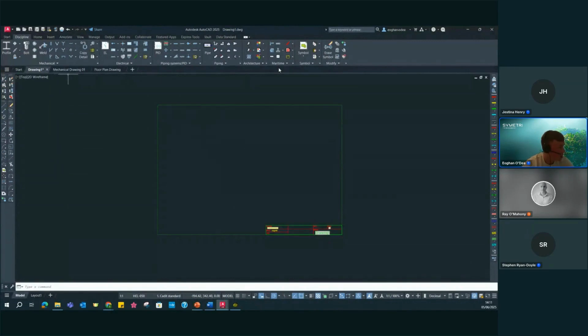So what we look at today is I'm just going to create a very simple P&ID drawing using the piping systems commands and the library, the component library. So you can see here I can come to this main piping command, and instead of having to change my layer to draw, say, a specific bit of pipe, this pipe work is automatically placed on my desired layer.